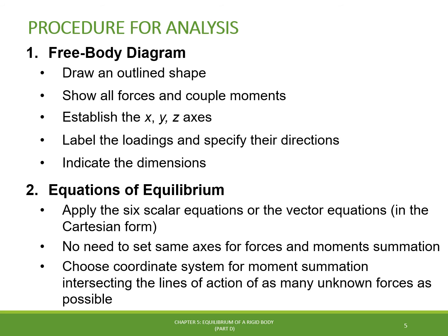And finally, we have to choose the direction of an axis for moment summation, such that it intersects the lines of action of as many unknown forces as possible. This will make the moments caused by these forces equal to 0, which will facilitate a lot the solution of the moment equilibrium equations.